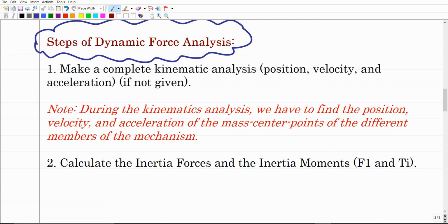But there is another thing, because you already have a project, so you have to do this in your project. You have to finish the kinematic analysis part, then move to the force analysis part. So what do you need from the kinematics to proceed to the force analysis? Or what data do you need from the kinematic analysis to do force analysis of the same mechanism? The main thing, basically, you need the acceleration terms.